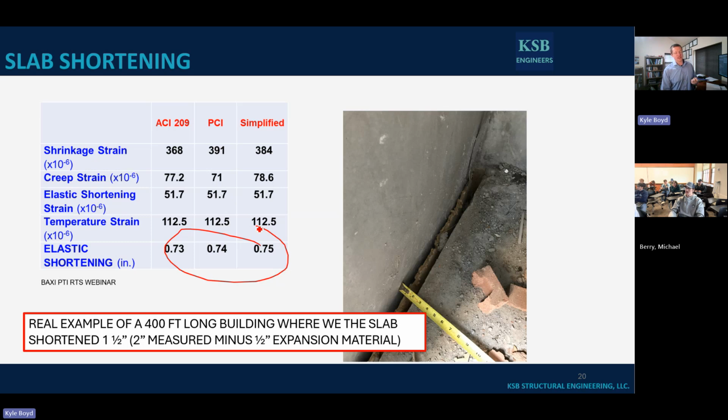If this is 3 stories below ground, is this slab bracing my foundation wall? Is it a lateral brace for my foundation wall? Is it a giant retaining wall for the 3 stories below ground? If that pulls off, no, it's not anymore. What's going to happen is the soil's going to push that wall in anyway. Am I okay with it from the standpoint that maybe I was a smart engineer and I actually designed a column right here, underground, that poured up against my wall but didn't actually hard tie to my wall? And so I do have a support right here, and it is pulling everything in. Sure, I'm okay with it. I've got the gravity support, but what about the lateral support?